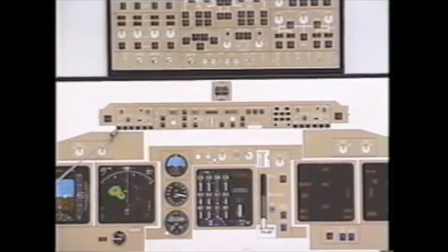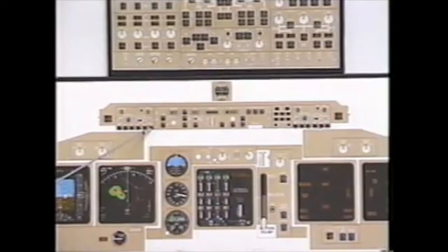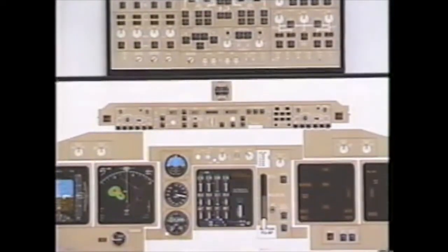Weather radar: this turns on the weather radar transmitter. So this is basically the weather radar on-off switch. Stations, waypoint, and airport: we'll turn on the stations, waypoints, and airports based on range, high altitude or low altitude. That is FMC generated. That would not be raw data. To actually pull up the raw data, select position, that would be raw data azimuth and DME to the station. Data simply turns on the time on the nav display at which you'll reach certain points.